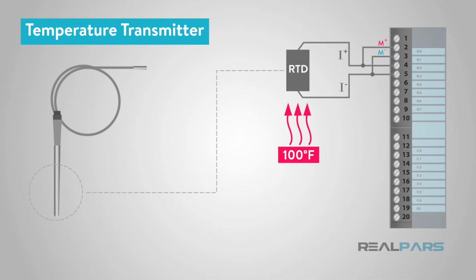When referring to such a device as passive, it means that the device needs an external current or voltage source. To state the obvious, a big amount of external current can cause power dissipation in the resistor of RTD and lead to excess heat. So, to avoid this type of error, the current should be kept at a minimum level.